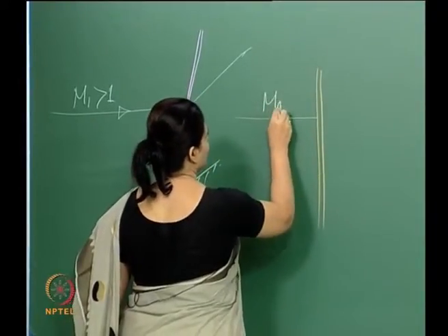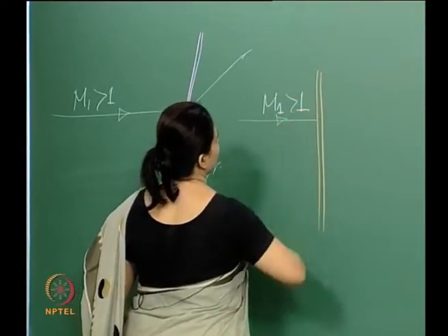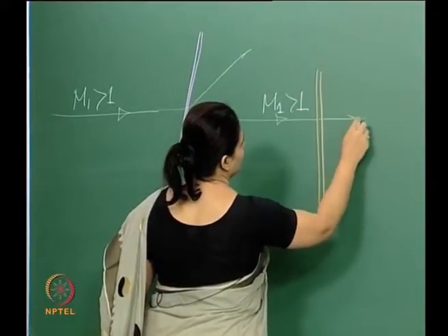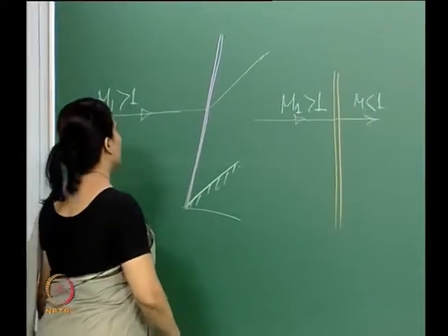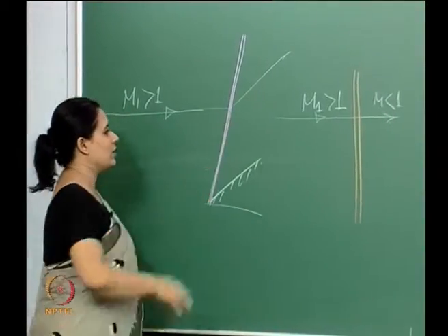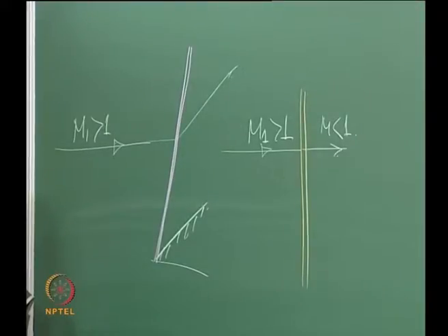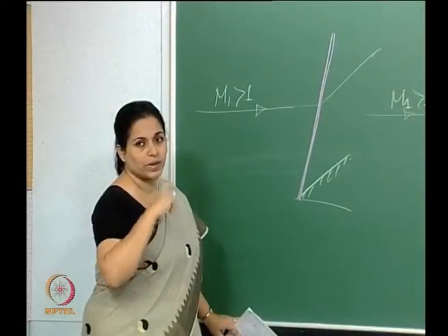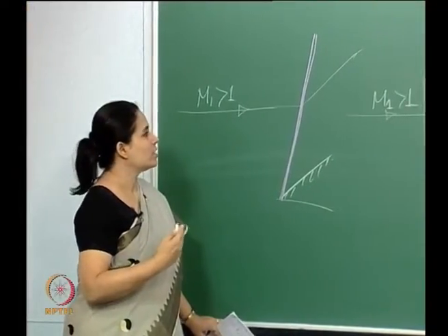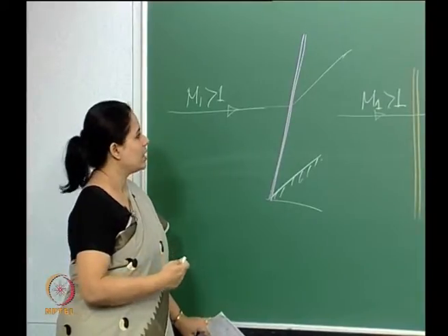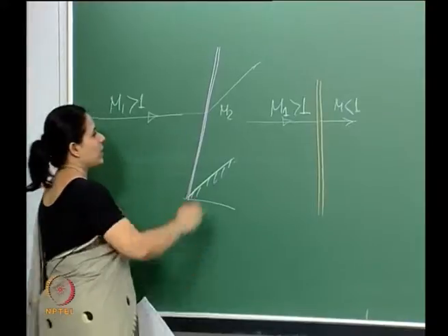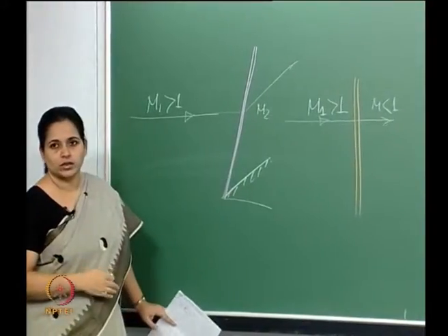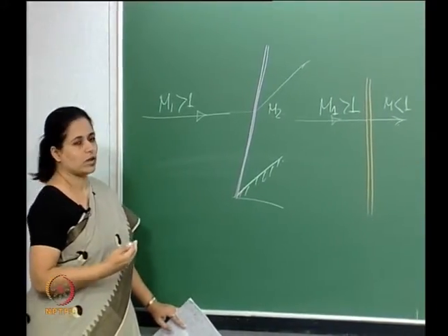So this is supersonic, and then this here becomes subsonic, and this here for, say, a blunt body could be a combination of subsonic and supersonic, depending on this Mach number M2, depending on whether this is an oblique shock, a strong shock or a weak shock.